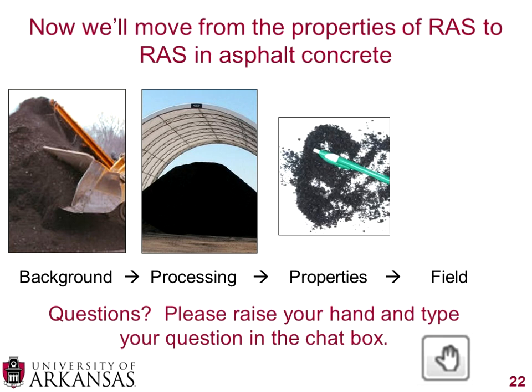So the question is, can you back calculate a RAS grade from a blended material? I would say that could give you an indication, but I would be extremely hesitant to put any sort of firm number to that because, like I mentioned, asphalt cement's not a linear material, so it's not necessarily a one-for-one switch. It's a nonlinear material over temperature and time.